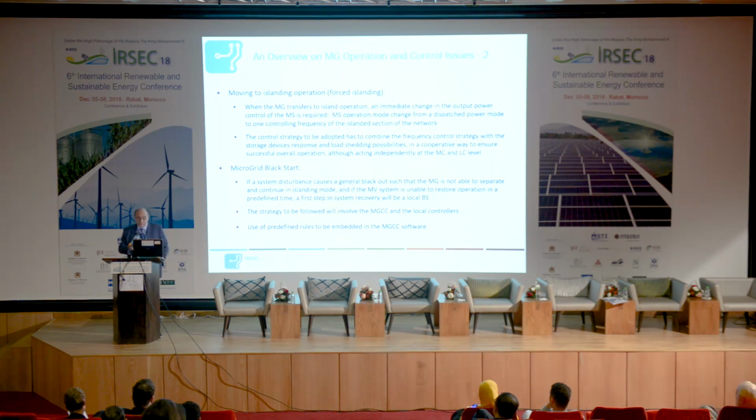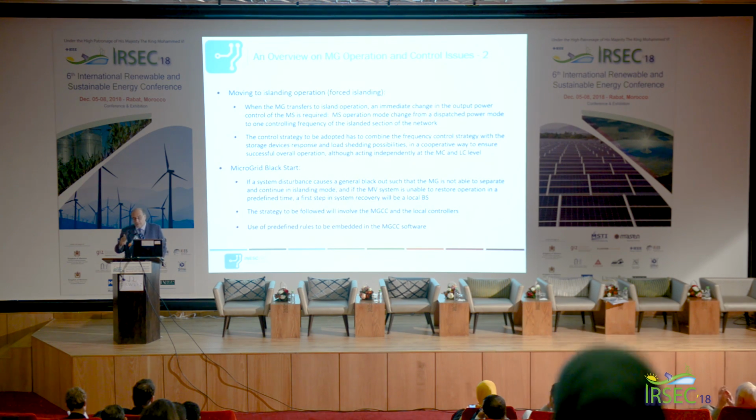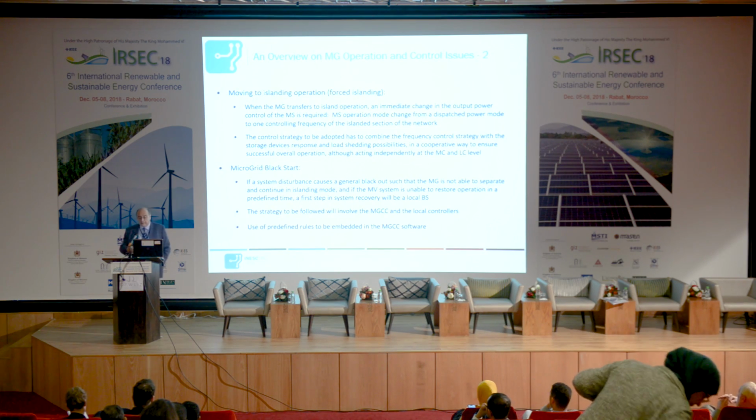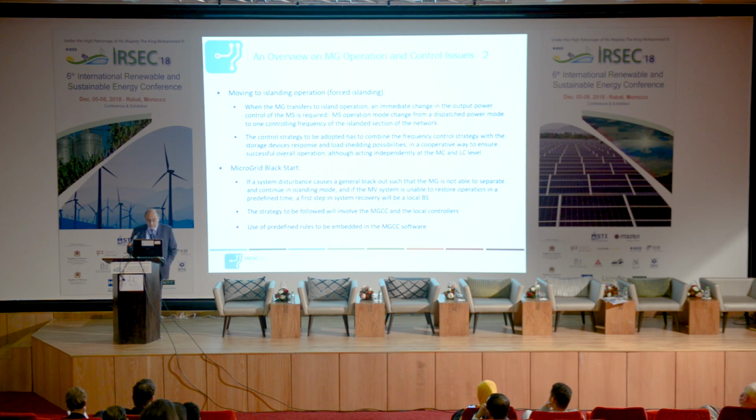Well, what I want to bring you here is a new approach. That is, since we have several sources distributed over the distribution network, and also if we have batteries that are capable to keep the balance in the operation of the system, why not make a local black start and solve the problem of the restoration of the system following a blackout, not from top down, but from bottom up? And in this way, create islands and afterwards synchronize these islands. So, that's what we have done.